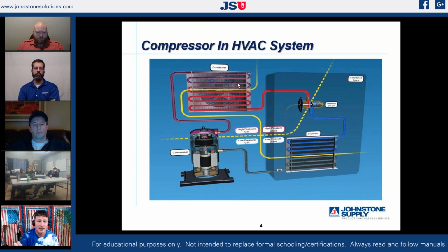And we're going to come right out of that pump, right into a condenser coil that is sitting in front of or behind our radiator. And we're going to use our engine cooling fan to move air across our condenser coil. We're going to come out of that condenser coil and go into a metering device. It's either going to be a piston or an expansion valve, and most vehicles in today's world use expansion valves. Some of the newer high efficiency luxury vehicles use electronic expansion valves.